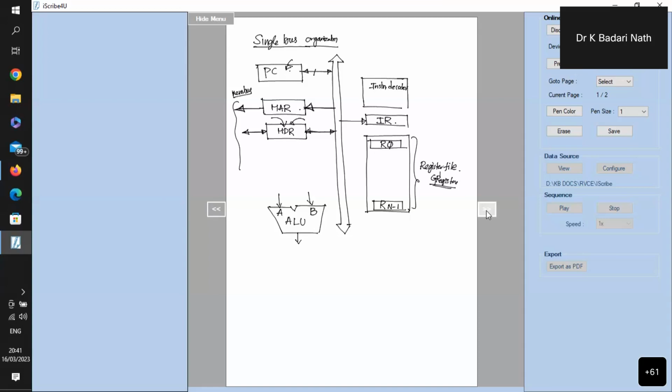If there are 3 bits, 2 to the power of 3, that is 8 meanings can be encoded. That means the decoder is the one which looks at the bits and decodes the information encoded in them. The instruction decoder and control logic is always connected to the instruction register. It will generate a lot of control signals. Some of these control signals go to the external memory and input output devices, and other control signals are connected to the different blocks present inside the processor.